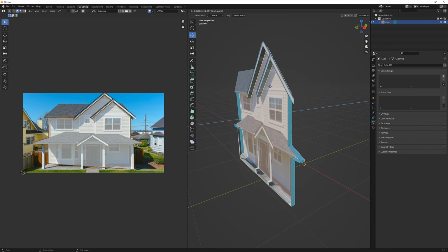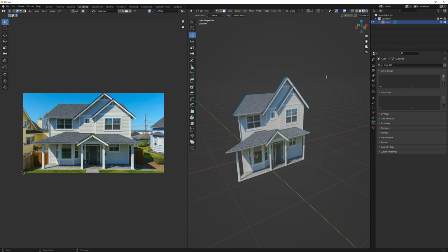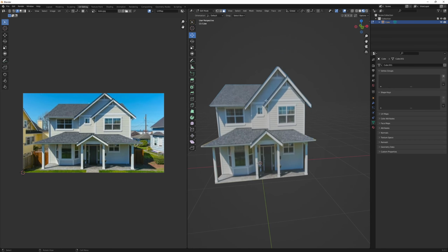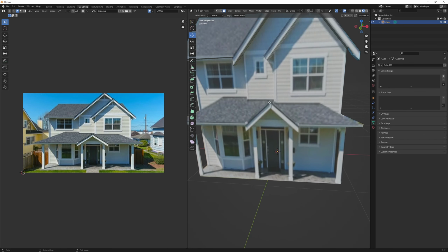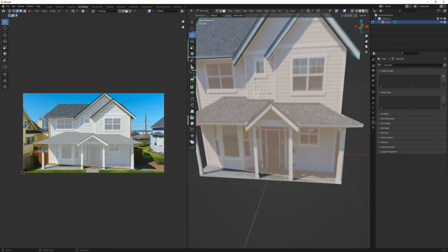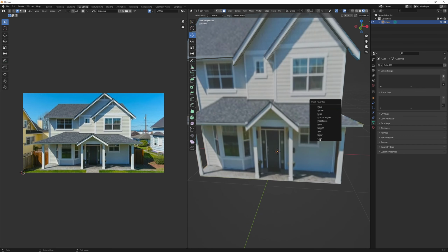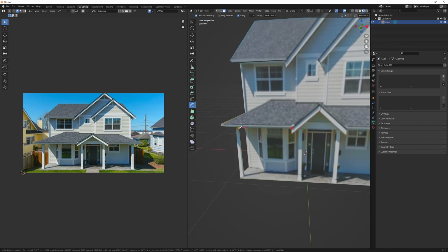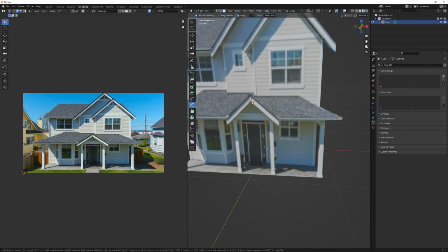But what I want is this bit of the roof to stand out quite well. So we're going to do the same for this bottom half here. We'll do the exact same here. Get a knife. And we'll continue doing this all the way down. And then what do I want to do here? So with this bit, we're going to just go along the edges. All the way down. Remember, this is going to be like an overhanging roof. Got to remember that. So we press enter.